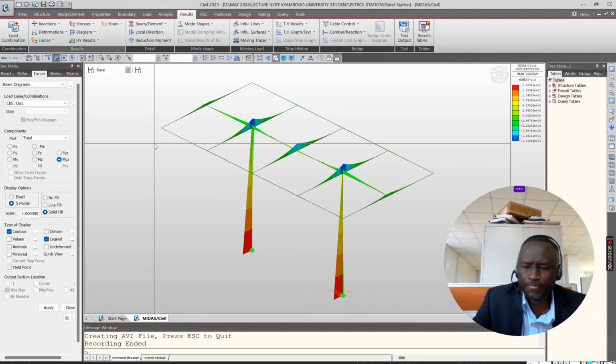So in brief, when you're doing design, you need to know, as I told you, the load path and the response of the structures. Very, very important. Once you understand critical areas, you should pay more attention. Once you do a model and you run the analysis, then you go to codes of practice and look at connection designs. The connections have got the bolts, the parent material you're connecting, and the plates.